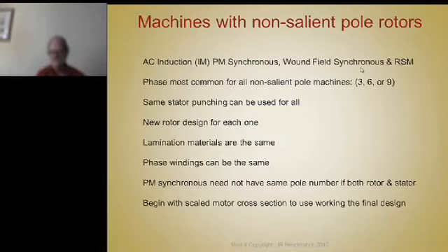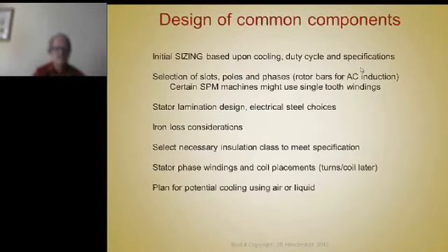And he would start with, we'll talk about sizing, but going through that sizing process, he would draw a sketch of the machine, and with lots of years experience, you can begin to pick diameters of rotor given the stator. You could pick tooth widths and yoke thicknesses and magnet thicknesses and things like that, just based on your experience. But to use that experience, you have to use a scaled layout or a scaled drawing to do it with. So that's very useful for machine design.